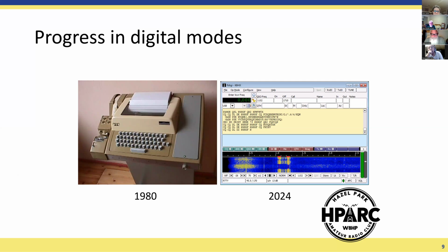And you'll see these two red things right below the scale, and two sort of vertical lines below it. That is a tuning indicator, and you want to get those two red marks on the two frequencies that are being transmitted.